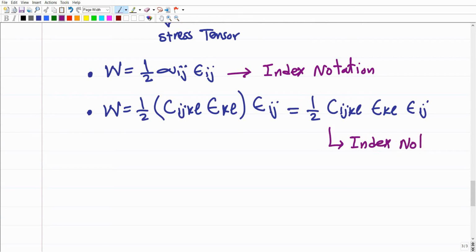The form that I recommend actually to use all the time, or to understand the strain energy density with, is this general form. It is recommended because all the advanced theories, if we're going to talk about the micromorphic theory or other advanced theories, the strain energy density should be defined in terms of the kinematical variables. But for linear elasticity, this term definitely is going to give us the stress. So that is fine to define the strain energy as the multiplication of 1 over 2 times the stress field times the strain field.